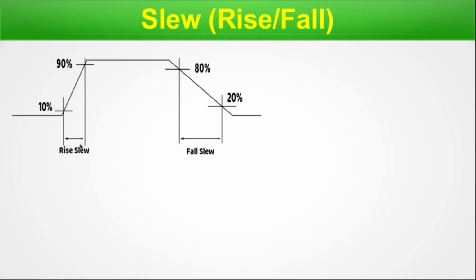Okay, this one. So this is called the rise slew. So here our thresholds are 10% to 90%. Our rise slew is measured like that, and our fall slew, again here it will be capacitive action, and it will be a bending instead of a sharp bend. It will be a continuous bending, and to accommodate a direct slope here like this, we have to cut it at 80% and 20%. And here in the time axis we measure the fall slew like that. So this axis Y is voltage, and this axis is time. So here we measure the rise slew, and here we measure the fall slew.